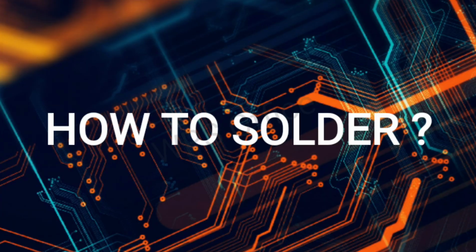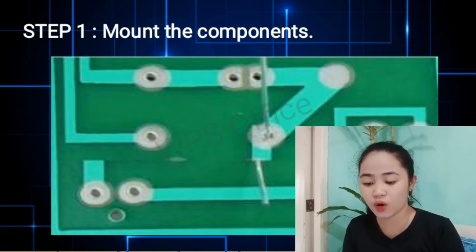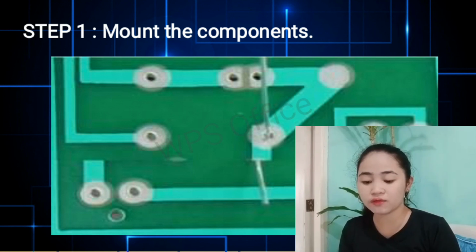And now we are going to proceed on how to solder. We have 4 steps that we will discuss. Step 1. Mount the component. Begin by inserting the leads of the LED into the holes of the circuit board. Flip the board over and bend the leads outward at a 45 degree angle. This will help the component make a better connection with the copper pads and prevent it from falling out while soldering.